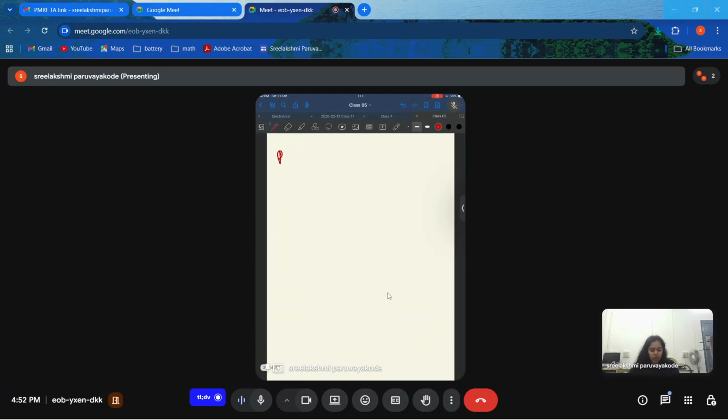Now the same question to find out RP, which is question number 14. Okay, so you have one here, one over here, one. This is 1000 ohm. RP means omega tends to 0. 1 by j omega c becomes infinity. That means this path won't allow any passage of current. Same over here. So for RP all the current should pass through this one. So the answer is 1000 ohm.